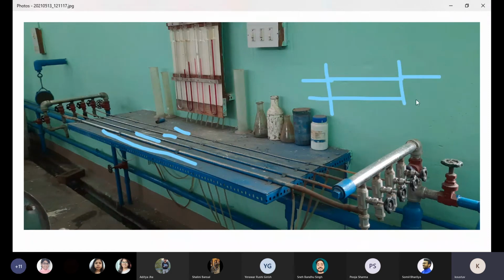The length of the pipe is very large in order to ensure that we remain in fully developed flow conditions. You all know what fully developed flow is: pressure across the flow path is no longer a function of y, it is fully a function of x, and velocity is no longer a function of x, but it is a function of y.